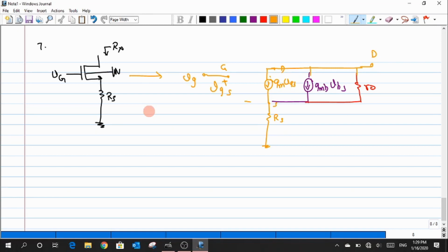First I will begin with step number 1. Step 1 is to fix a voltage source Vx across the node at which I am trying to find the output impedance. The second step is to kill the independent source. In this case, Vg is the input source, which I just kill here. So I have connected the gate potential to ground, and the third step is to measure Ix.